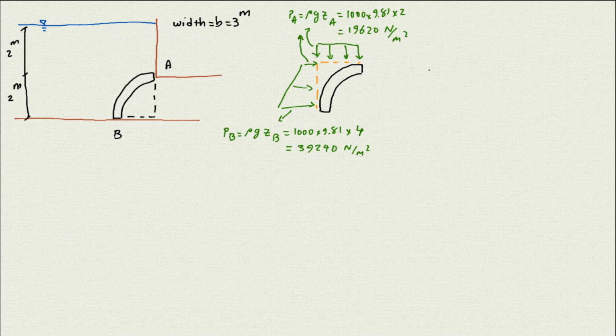And then here, as we said, I didn't draw the third dimension, but it's a 3D load, so it's the pressure on the surface of the gate throughout the width of that. But we want to convert this 3D load to a 2D load, and to do that, as you remember, because we assumed the pressure is not changing along the width, whatever we have here is going to be constant across the width, so we just multiply all the pressure by the width. So I'm going to draw that gate again here.